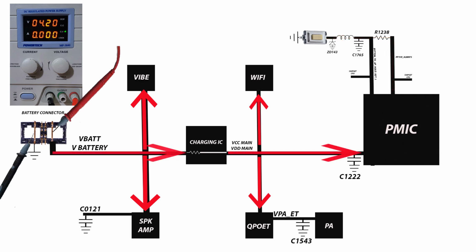0 on the current. This is the normal phone. If before pressing the power button there is leaking or a short circuit showing on the DC power supply display, showing 1 milliamp, or a short of 2-3 amps, that shows current leaking. That means you have an issue in there. But before pressing the power button, normal phones need to show 0. This is the first thing for troubleshooting.